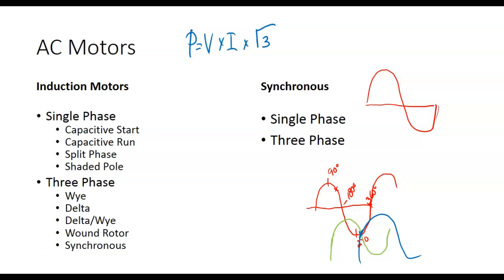So three-phase motors automatically generate a rotating field. You can see this. When A starts dropping down, B comes up, and it just constantly does that. Three-phase motors are a lot more efficient than single-phase motors, but they cost a lot more money. So if you need a lot of high torque and really good efficiency, then three-phase motors go. Single-phase motors are very, very cheap. But we have to create a shift in the phase to cause them to do what?